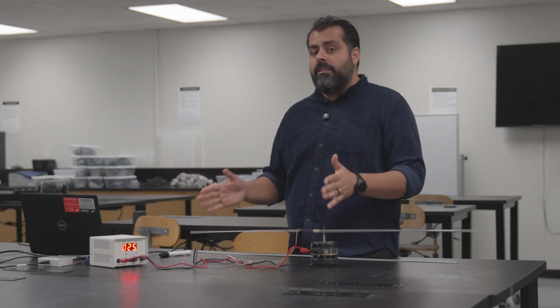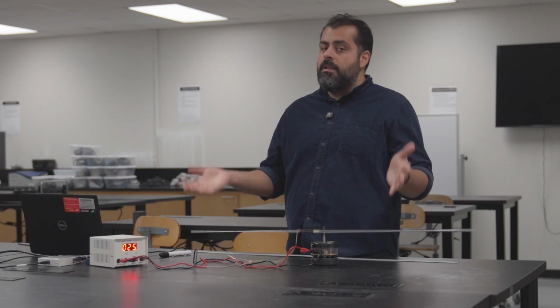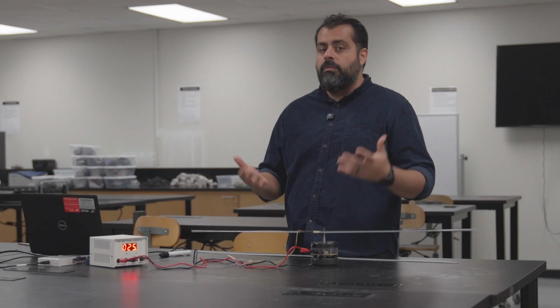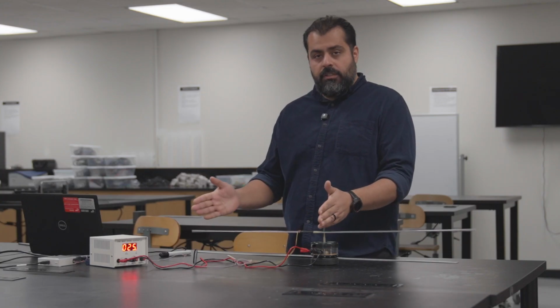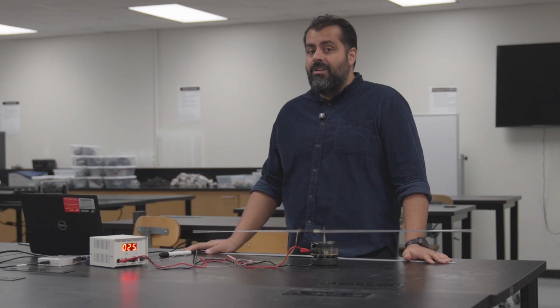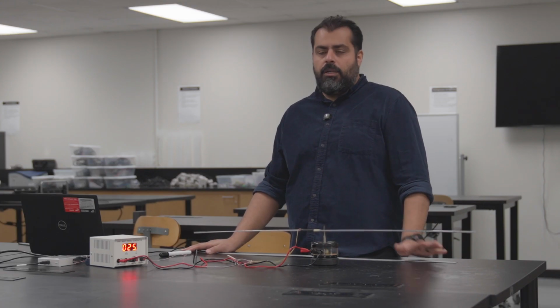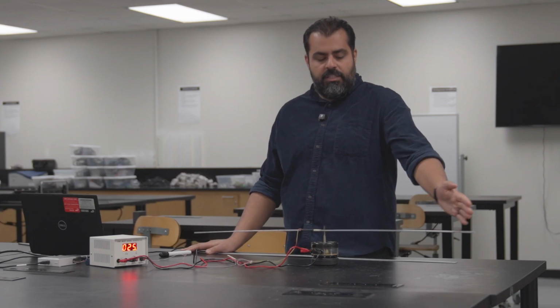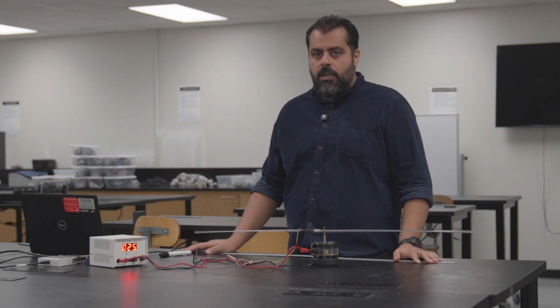Do we need to make the 2 measurements for the cantilever beam? No. But if you do make the 2 measurements for essentially 2 sides of the 2 cantilever beams that we have, you have to make sure you average them out and find the confidence interval, essentially find the uncertainty. But you don't need to do that. Just 1 measurement from 1 side of the cantilever beam should be enough.